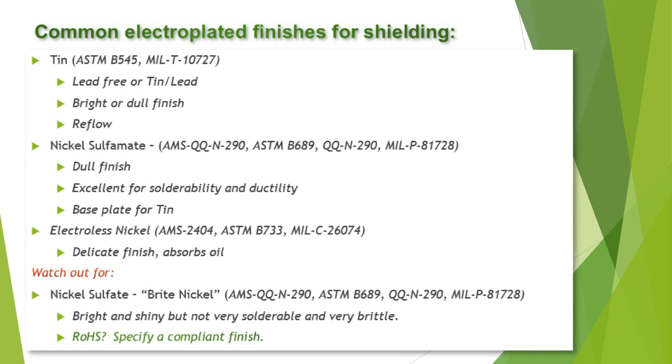Okay, so just to point out as a note here before I move forward, if it's a requirement of yours, please don't forget to specify lead-free or RoHS compliant plating. Sometimes the specs can be very similar and you don't want to end up with a part that you cannot use. Anyway, to get back to the finishes, let's talk a little bit about sulfamate nickel, which has a fairly dull finish, but it's excellent for solderability and for shielding.